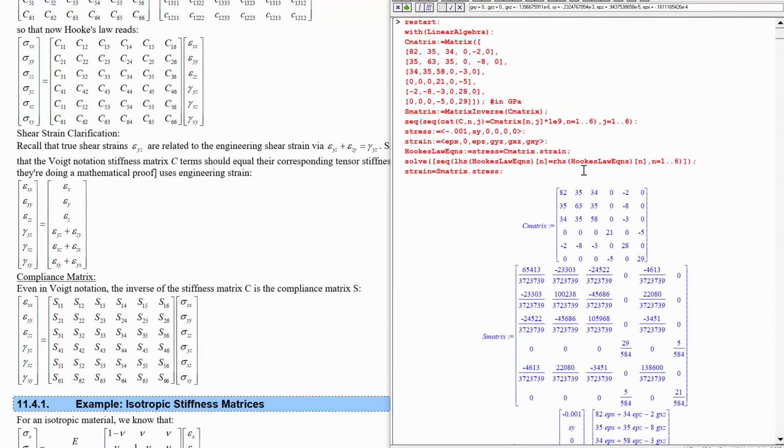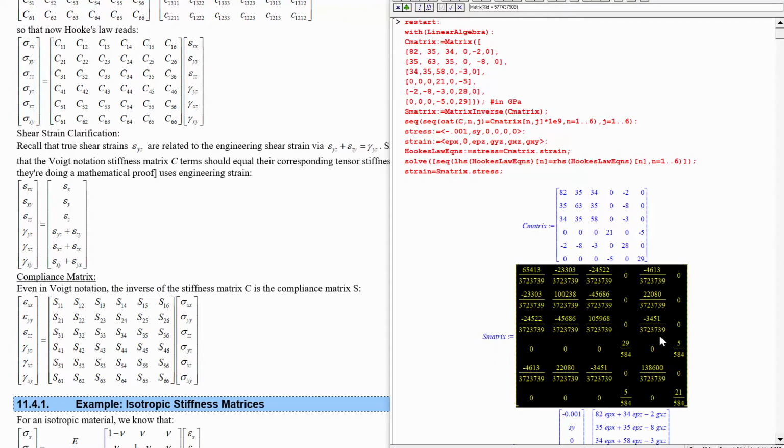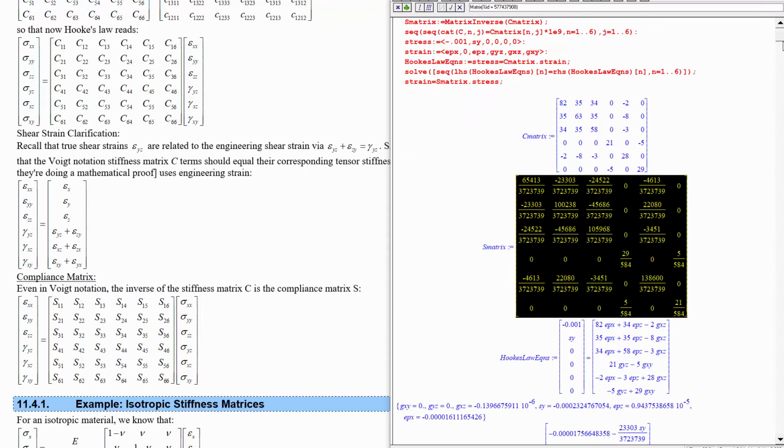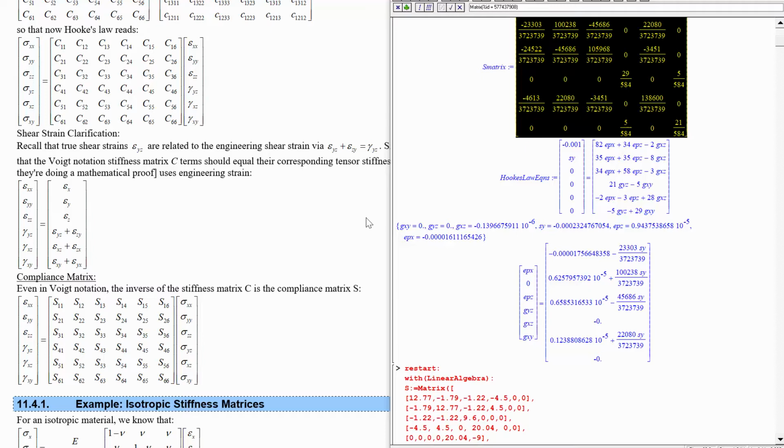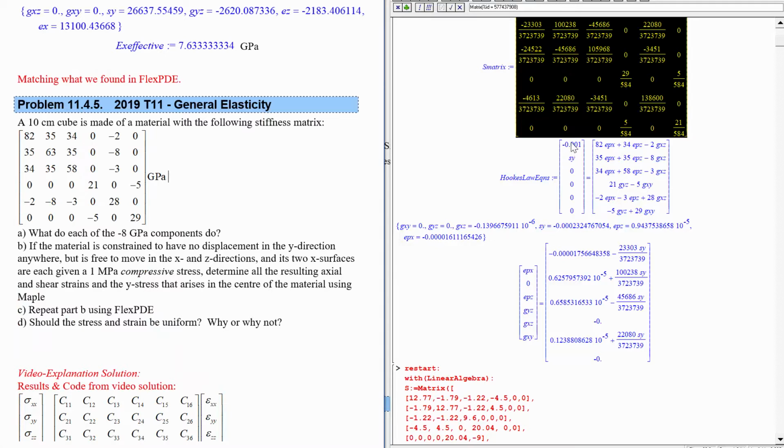So that's how you can take the set of material parameters and incorporate them into determining what the stress and strain need to be when you're given enough of the parameters of the boundary conditions that the material is in. So in this case, we are told that we have this compressive stress in X, and it's free in all the dimensions, except that it's fixed to have no Y displacement, and that leads to information about what a lot of the stresses are, but only one of the strains. If you knew that it was fixed in 2 dimensions, that would also be fixing some of those shear strains. It didn't completely eliminate some of them this way. They just happen to end up being 0 because of how we were loading this material and its anisotropy.